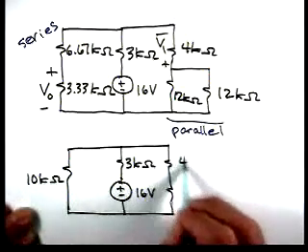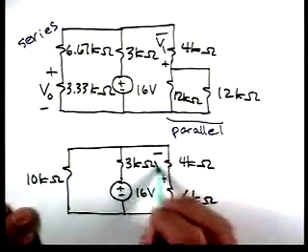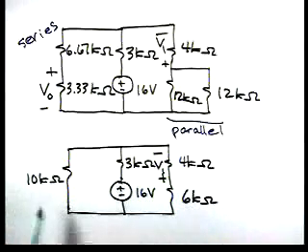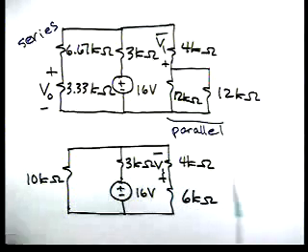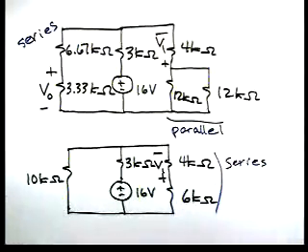Our circuit is reduced to the following. The voltage V1 is still across that 4K. We've lost the voltage V0 now because we combined that 3.3K in series with that 6.67K. So now these two are in series, so we can draw our circuit again to reflect those combinations.